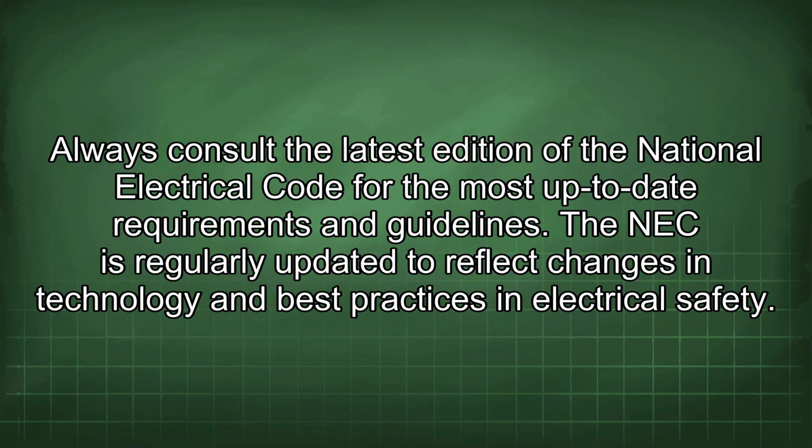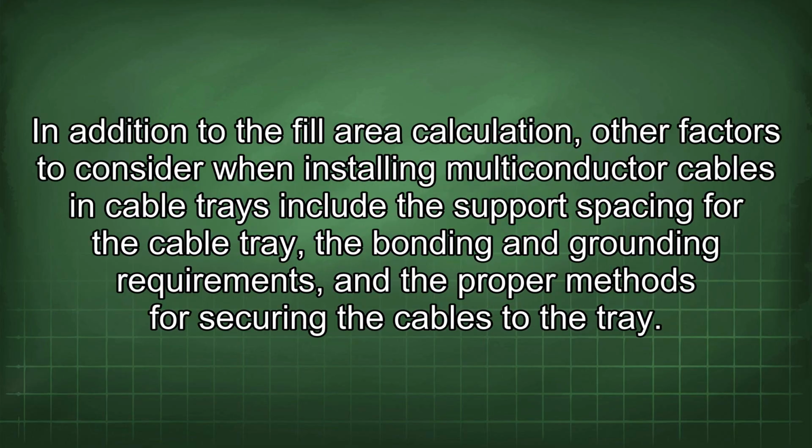Always consult the latest edition of the National Electrical Code for the most up-to-date requirements and guidelines. The NEC is regularly updated to reflect changes in technology and best practices in electrical safety. In addition to the fill area calculation, other factors to consider when installing multiconductor cables and cable trays include the support spacing for the cable tray, the bonding and grounding requirements, and the proper methods for securing the cables to the tray.